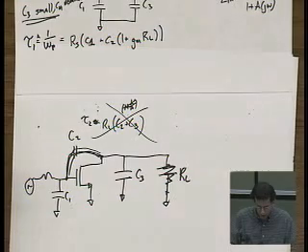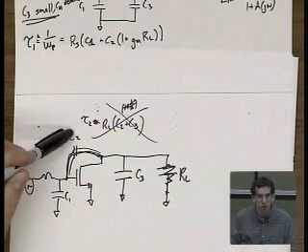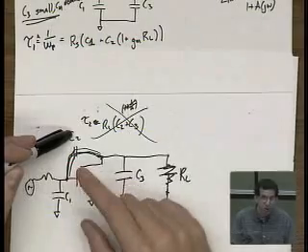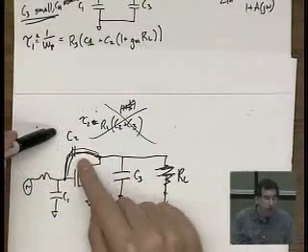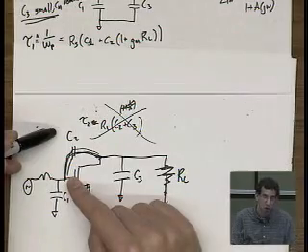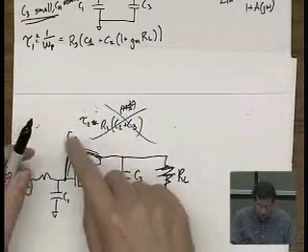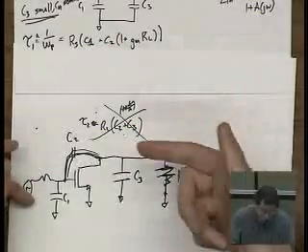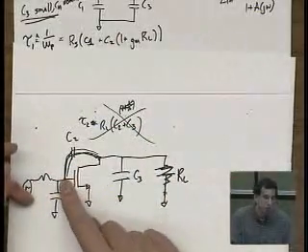Yeah, and this really comes down to how big C2 is. If C2 is big, then at the higher frequencies, this capacitor will look like a short. So at high frequency, yeah, you could just put this over here, but the point is that at high frequency, you're looking in this direction, you see this node.